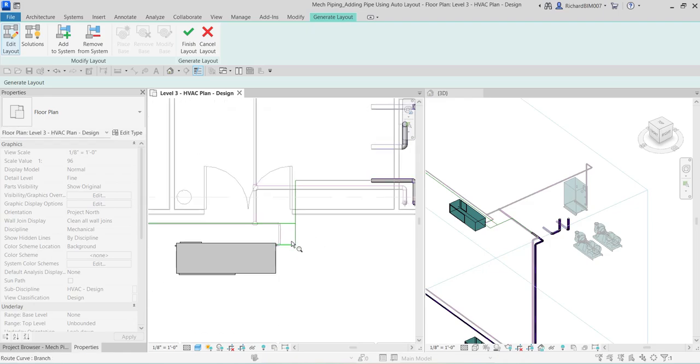Just to tidy up, not too close, because there are some instances when you finish the layout that an error occurred. An error may occur while you are attempting to create pipe geometry as a result of converting a layout during sizing. The most common cause, which is the reason why we are adjusting our layout, is if there is insufficient space to create the pipe or the offset elevations are incorrect. That's why we also change the offset.